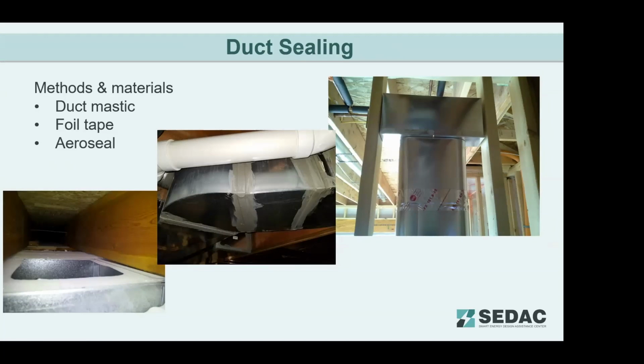Methods and materials for duct sealing. Well, on the lower left, if somebody's failed a test, this is what they're hoping to find. It's some big hole where it takes them just a couple minutes to seal it up. You retest, pass or fail. But in my experience, it's almost never the big hole. It's just a collection of small holes.